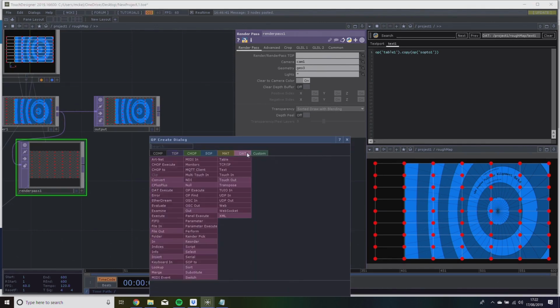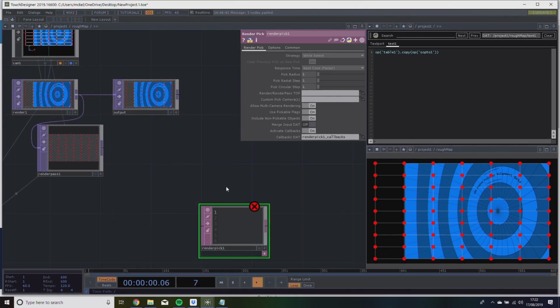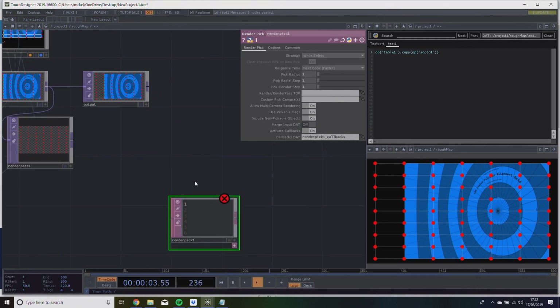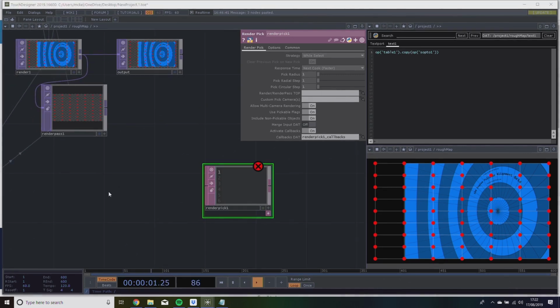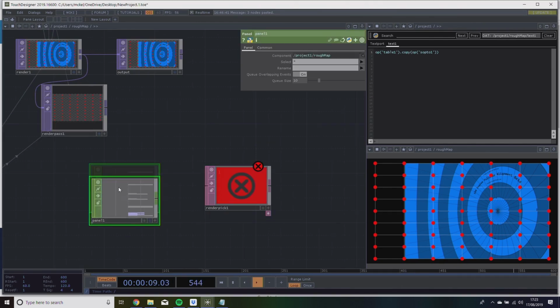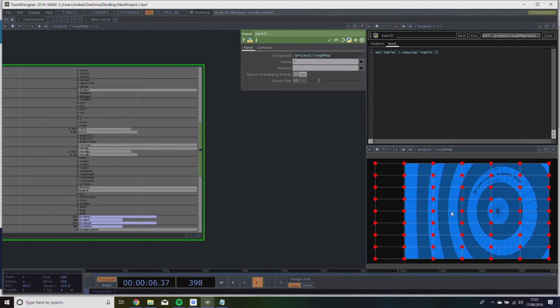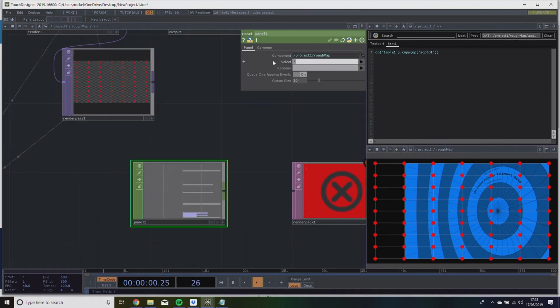Now we're going to double click and add the DAT called render pick. Now the render pick is really brilliant, but also really fussy. So it needs very specific parameters passed into it before it will even start to work. And those parameters it needs, if we go to the chop tab and search for panel, now the panel is going to give us loads of information from the container that we're inside of, like mouse position, what I'm clicking with, how many times I've clicked. But we're going to isolate them down to just the U, the V, and the select. So inside here, instead of asterisks, I'm going to type U space V space select. And that's going to give us just our U, just our V, and whether the mouse is being pressed or not.